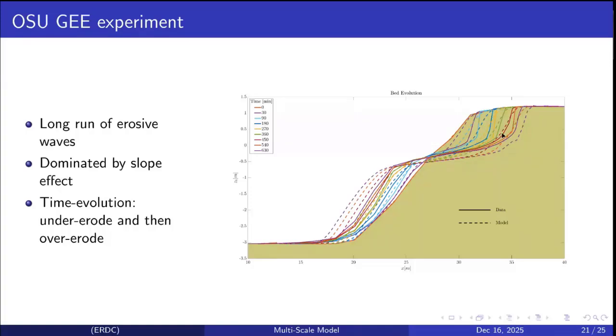There may be infragravity waves in these regions that are happening hydrodynamically that I'm not including at all, which is another reason why, if I had more detailed data for this experiment or any experiment, I could include those measured hydrodynamics in waves rather than predicted ones. But again, if anyone has any ideas about why I would initially see an under prediction of the morphology change and then finally an over prediction of the morphology change, I'd be interested to know what people think.